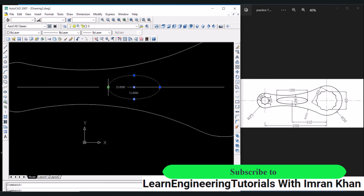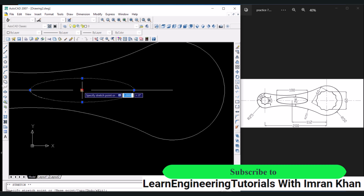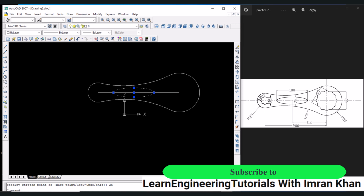So we will click on this side, move in the positive x direction, and the tracking is formed. We will just write 50, enter. Now the ellipse is OK. Let's look at its place. So we can see that from here to this end point the total distance is 87, right? It should be 112, so that means in this x direction this ellipse has to move by the distance of 25. So we'll write 25, enter, and now this ellipse has been placed correctly.